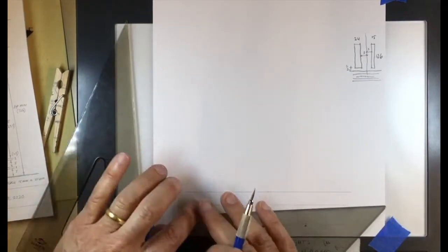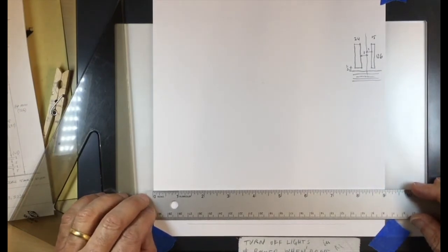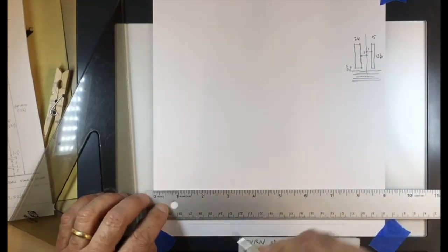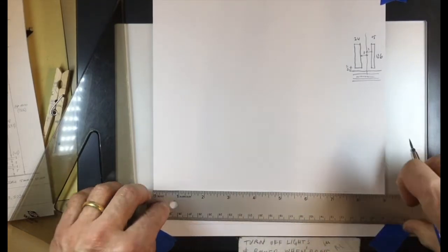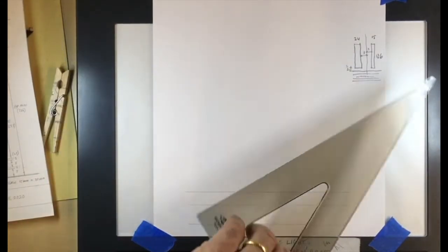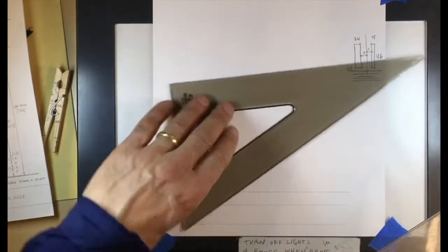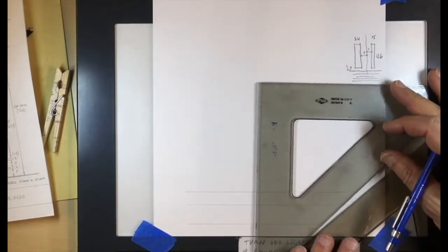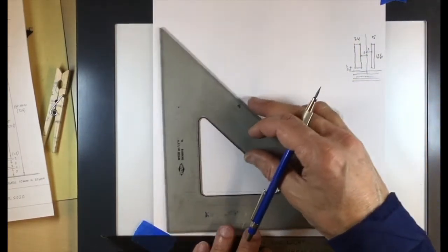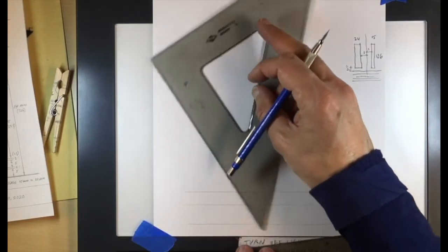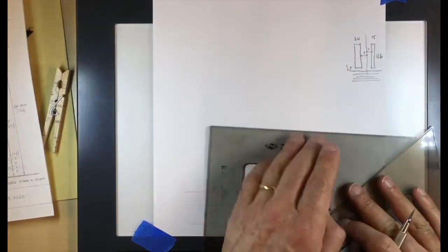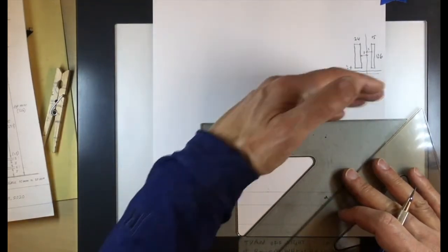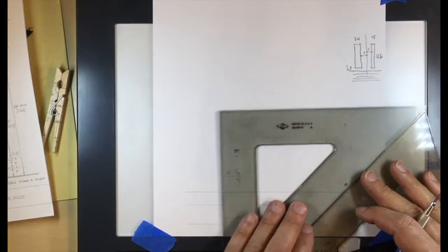You would be going all the way, right? Since you have all your construction. Then we have the center line. So again, it's 9 inches from edge to edge, so 4.5. And now, since I don't have your straight edge, I can do it 2 ways. Again, I can trust the edges of the paper. Another thing I could do is I could use my triangle to get a perfect vertical of my horizontal by actually sliding my triangle this way.